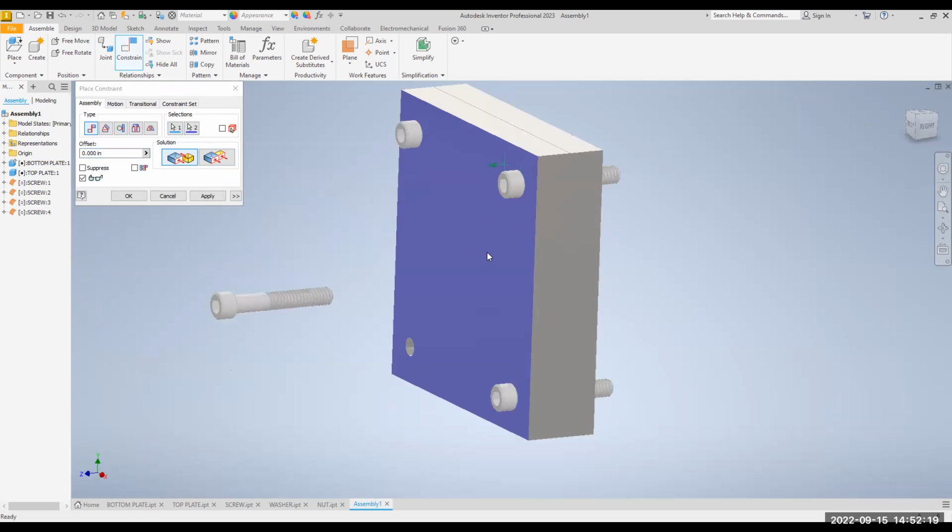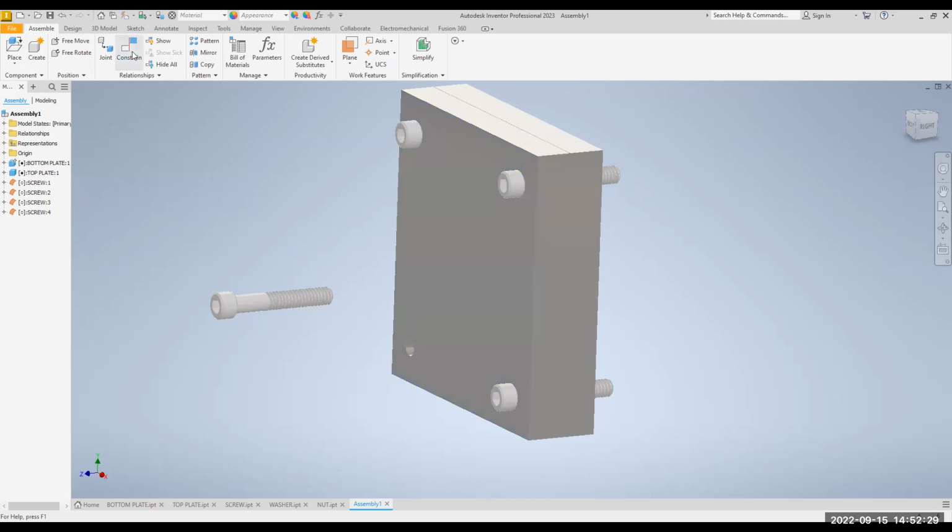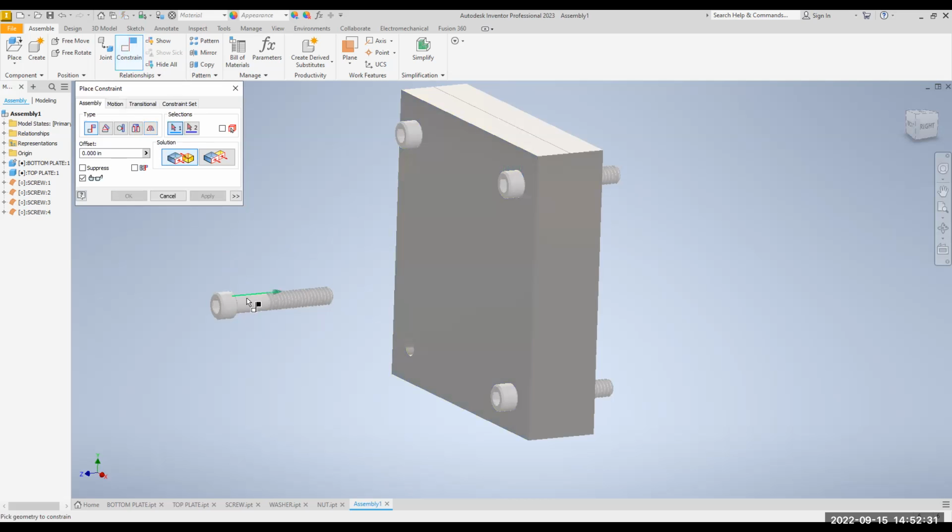Again, like I said, I hope this video is going to record. It's been a long time since I made a video in this class. Okay, one more to do. Go to constrain, hover, center line, click, come over to the hole, hover, center line, click, select OK.